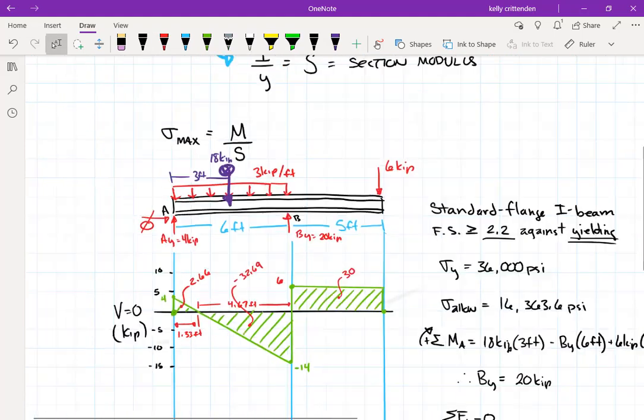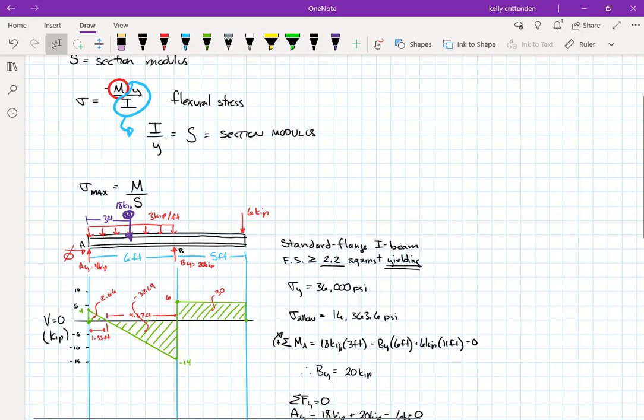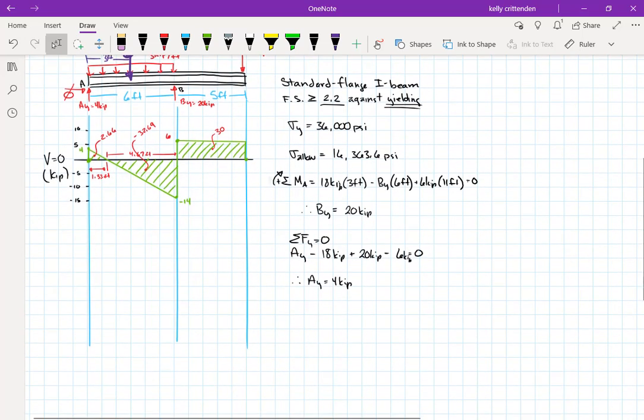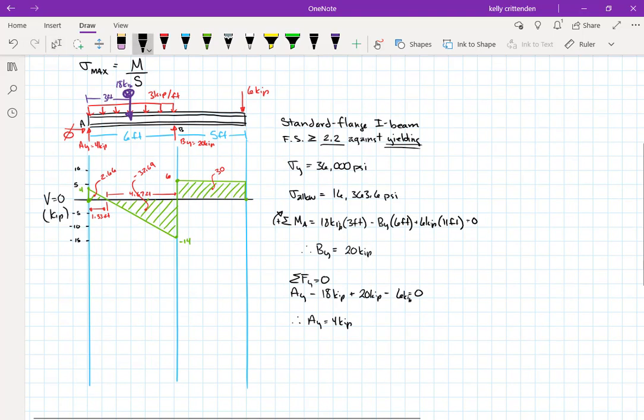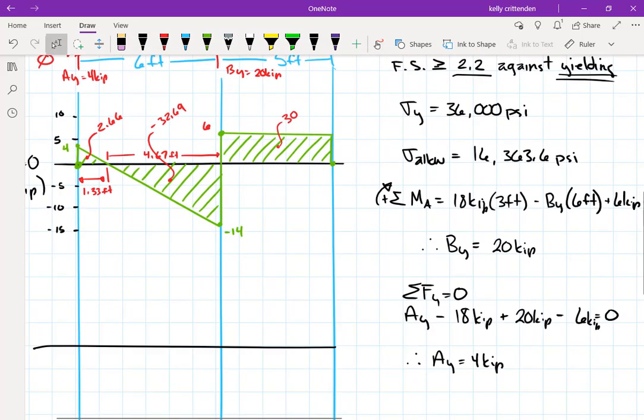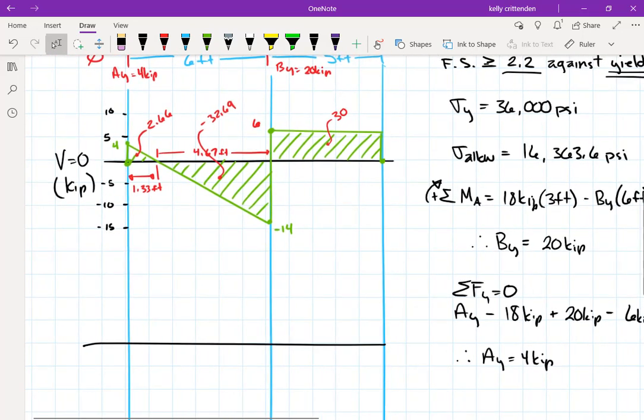So I have to zoom back out to work on where we're going to put our bending moment. This one didn't have any concentrated moments in it, so we don't have to worry about that. I'm going to put this bending moment 0 point right in there, and we'll try and get all these visible. So this is moment of 0, and the units are foot kips, kip feet, whatever order you want to put those. Normally you put kip feet, but normally you put foot pounds. Although foot pounds normally is talking about a torque, which these are not, we're not going to call them torques. They work the same though.